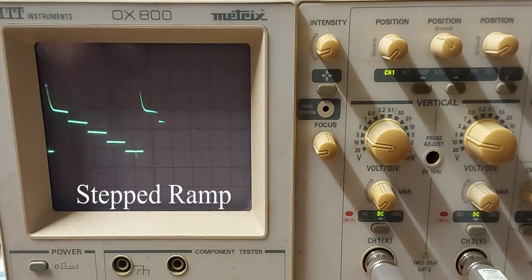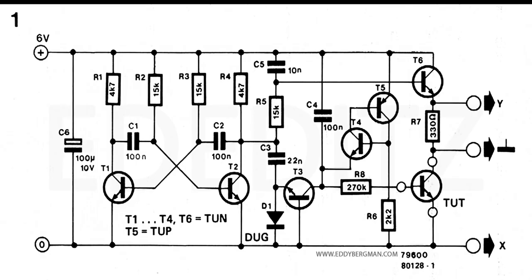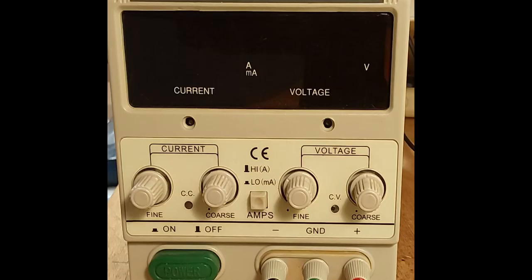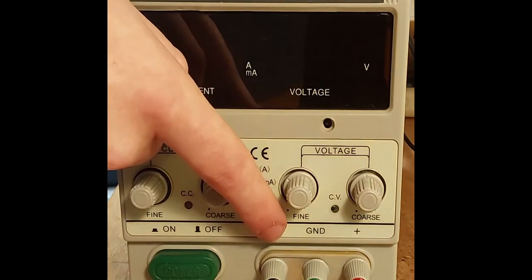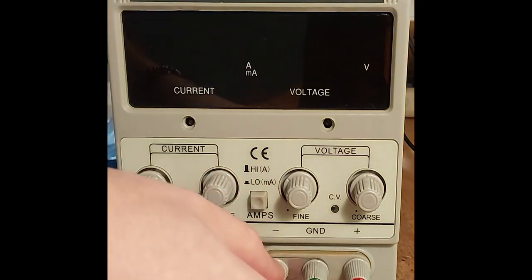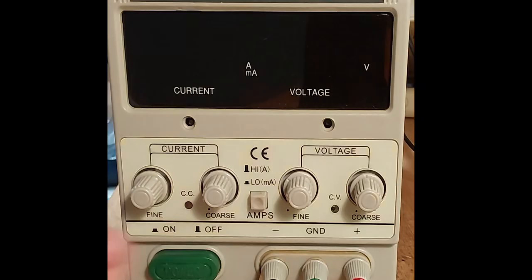Now, if you're gonna build this circuit, just one important recommendation. You need to take a floating measure with the oscilloscope. Otherwise, if the ground of your circuit is connected to earth, when you put the ground of your oscilloscope at the collector of the transistor under test, you'll short it out. Usually, power supplies give you the possibility to disconnect the ground and earth. Mine, for example, has this little metal sheet which I can unscrew. If yours doesn't, the best way is to power up the circuit using a battery.